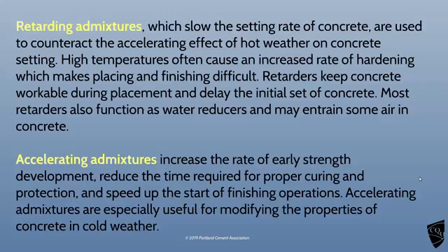You can accelerate it if you want to get early strength, but you won't have much time to work with it, so it may only be used where we just pour it straight into a bored hole to make a pile or a pier foundation or something like that. Especially used in cold weather, these are.